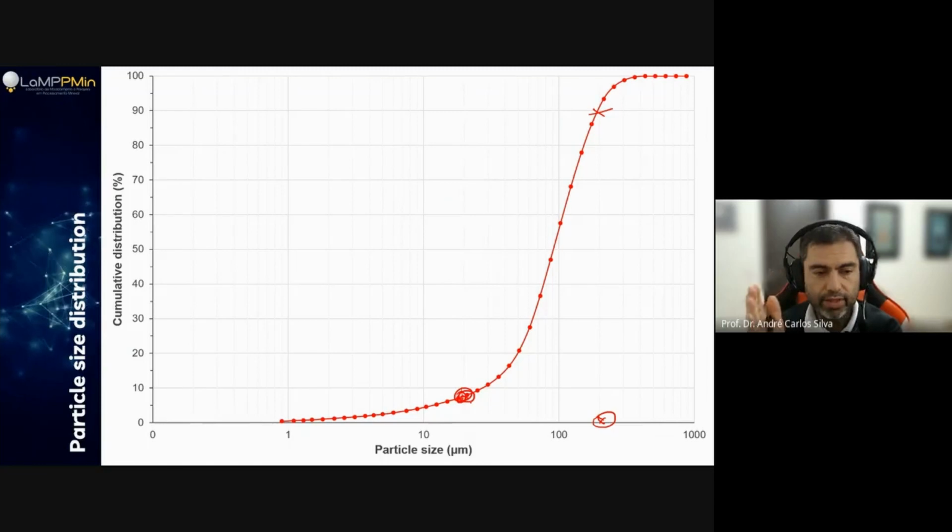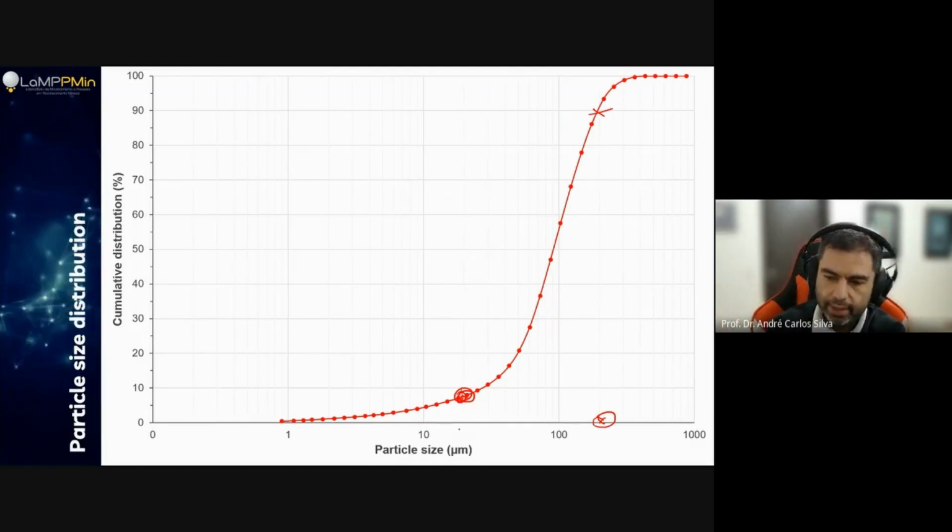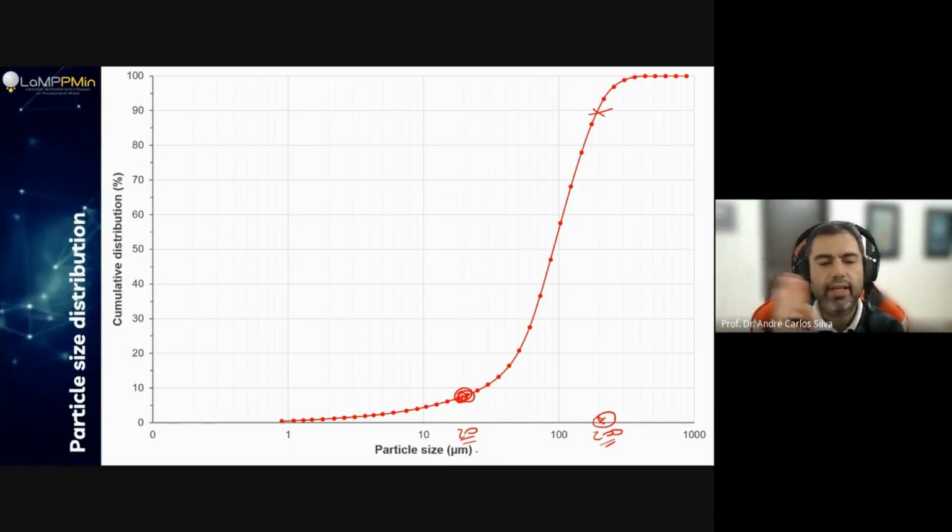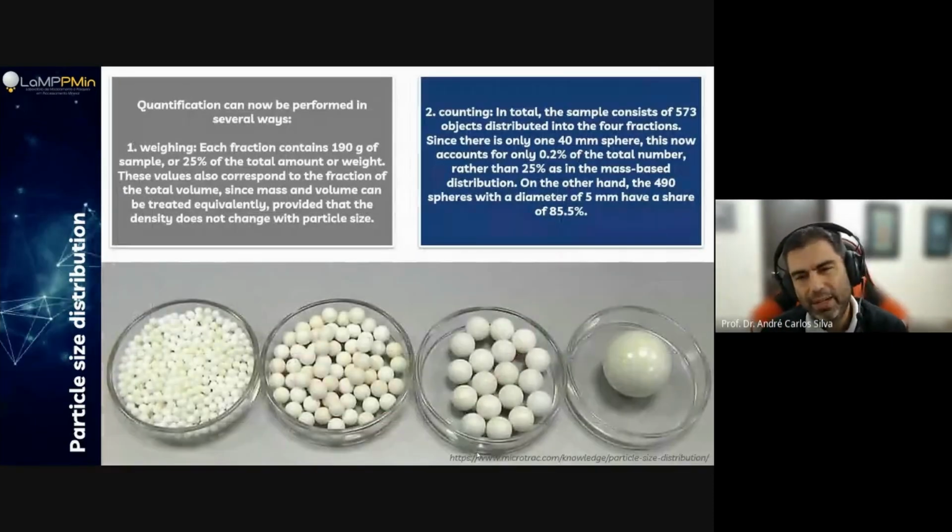Okay, I don't want to tackle this, it's too fine. And how much material am I going to lose to the slime fraction? Oh, less than 10%. Okay, I can work with that. And why am I telling you guys those numbers? Because from 20 up to 200 is normally the threshold for flotation for our main concentration. So just looking at this, I can have a glimpse of what I'm going to have in hand. But that's quite tricky, because let's consider this example over here.